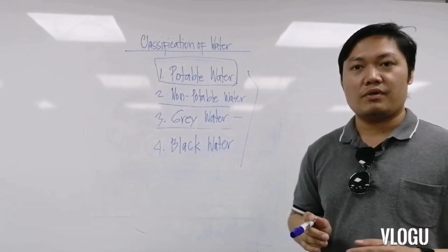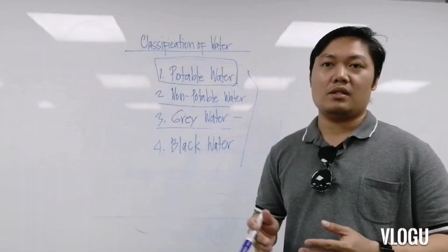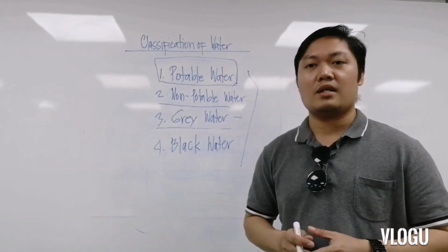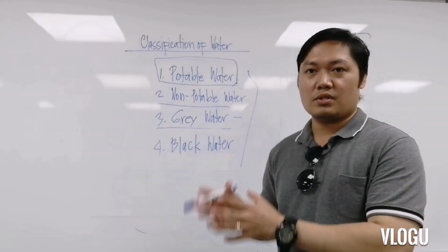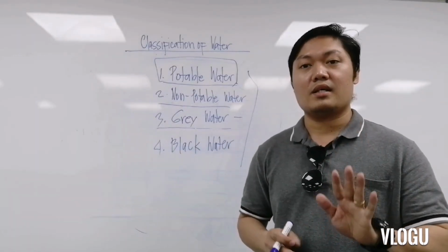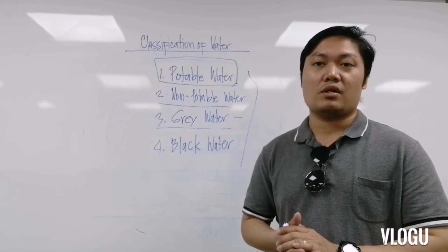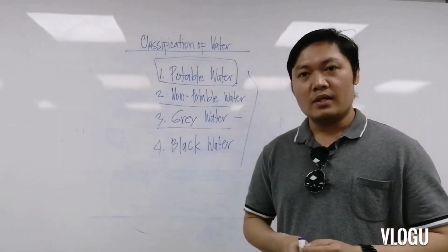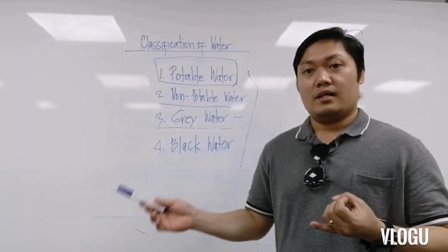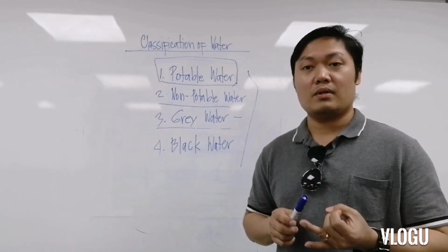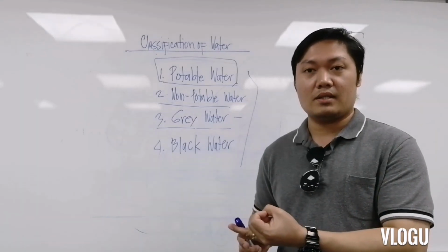First things first, before we proceed with this type of activity on site, we are going to ensure that all the necessary documentation is in place. We are going to identify the types of documents you are going to prepare before work execution. The main document is the material approval request, or known as the material submittal.